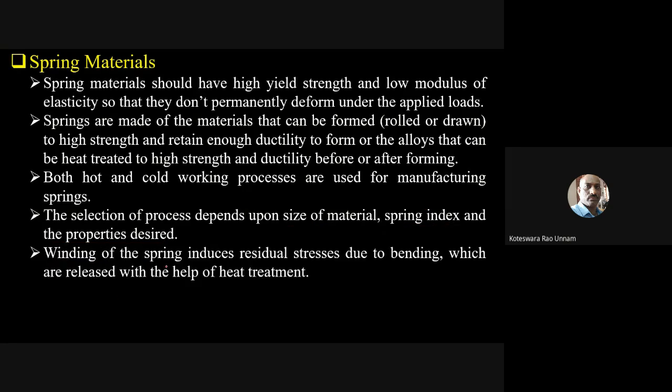The bending of the spring induces residual stresses, which are released with the help of heat treatment. Like we already said, in the case of helical springs, you take a straight wire and it is wound in the form of a helix.